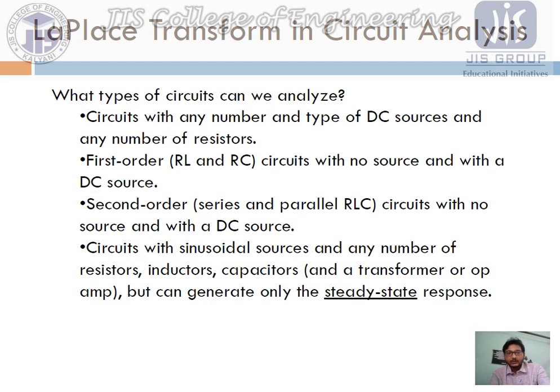Now, what types of circuits can we analyze? We can analyze circuits with any number and types of DC sources, and any number of resistors, inductors and capacitors. Similarly, first order circuits consisting of resistance and inductance, or resistors and capacitors, with or without a source, with a DC source or some AC source, we can calculate using this Laplace transformation.